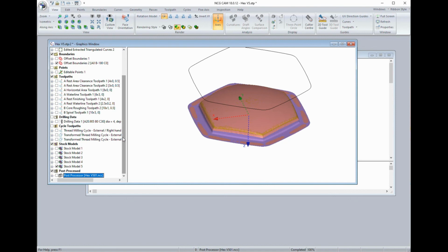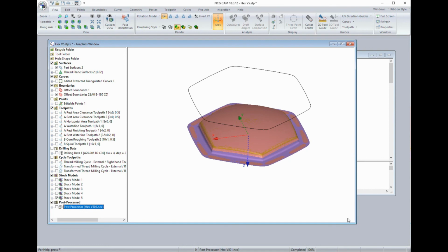And that's quite easy. All the post processors for 3-axis are part of the system. So basically if you have a FANUC control, you start off with a FANUC standard post, and then there's about 400 different parameters you can change to make it specific for your machine.